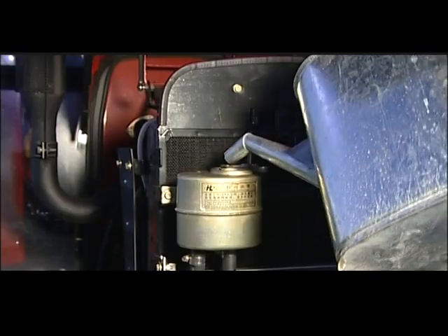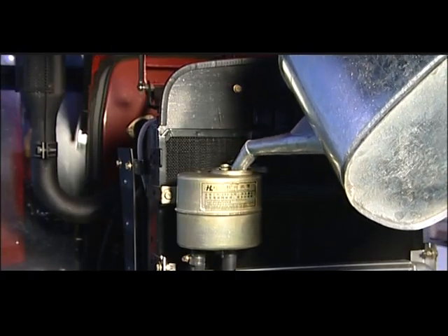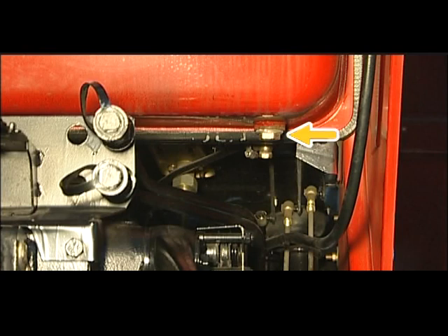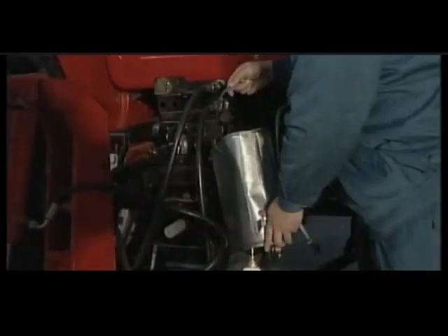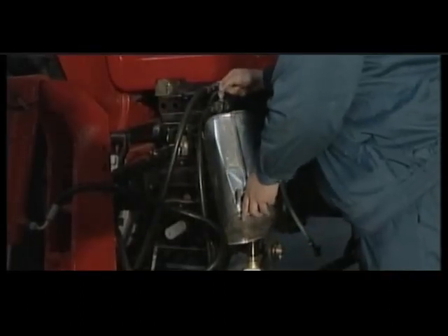800 hours technical maintenance: full contents of completing 400 hours technical maintenance. Change the lube oil in the steering oil tank. Unscrew the drain plug at the bottom of the fuel tank. Drain the impurities. Change the lube oil in the transmission system and hydraulic system.